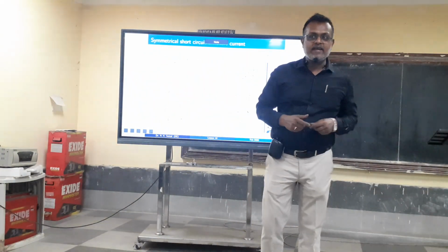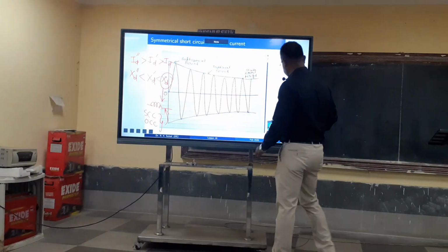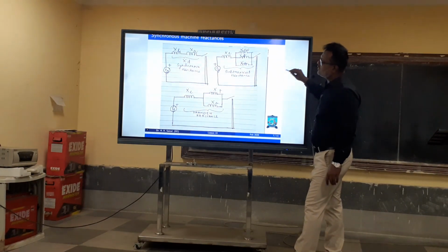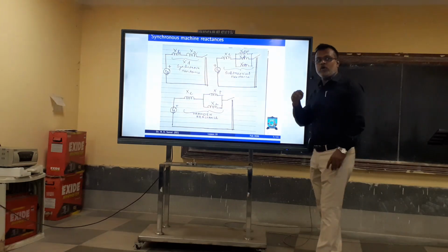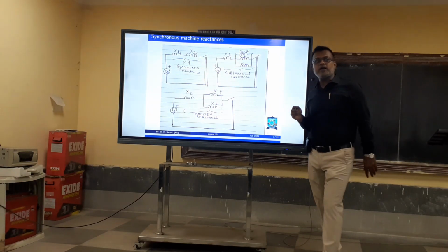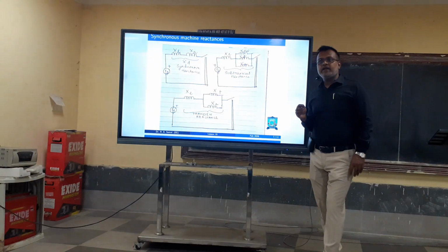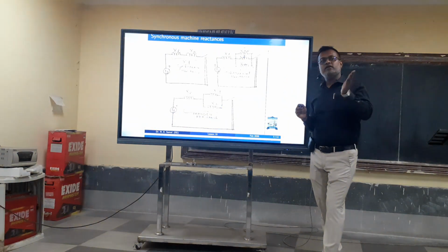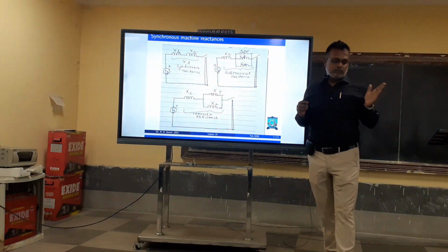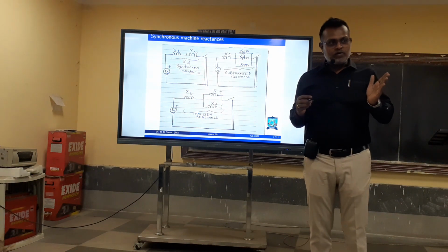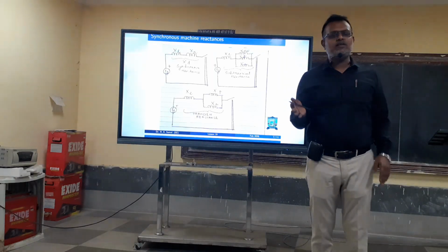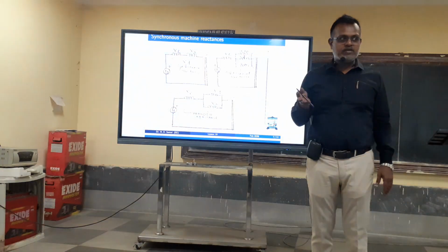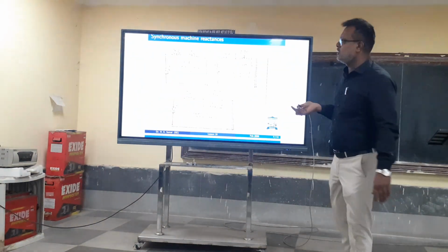Okay. So why exactly does it happen? This is the theory that has been put forward to explain the behavior, of why the alternator provides the lowest reactance in the initial fault period. Actually, that is a continuous process. The reactance is slowly increasing, but we have decided to categorize it into 3 types only: subtransient, transient, and steady state.